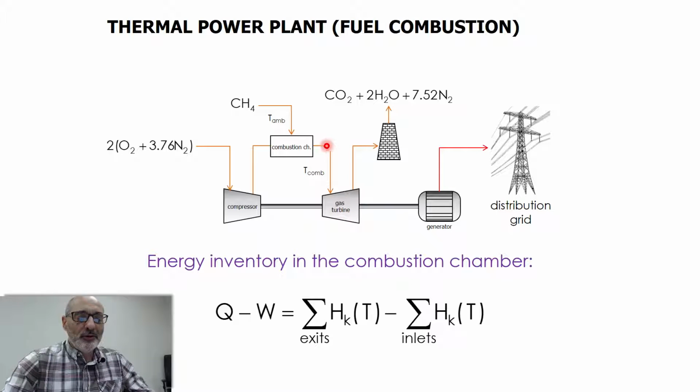Okay, so here you have hot gases, high pressure. They are expanding on the turbine, generating mechanical work. Part of this work is used by the compressor, and part of this work, the surplus work, actually drives the generator. Okay, and then you exhaust gases to the atmosphere.